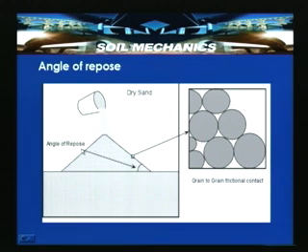What we are saying is that it can increase with the diameter of the particle. If you look at the microscopic view, grain to grain frictional contact will be there, and with that it exhibits this particular type of structure. As you are pouring sand, after reaching this angle of repose, the soil starts slipping. That means that is the safe slope at which the grains can stand. But if the same soil is made wet, it can even remain vertical; the angle of repose can increase very, very high.